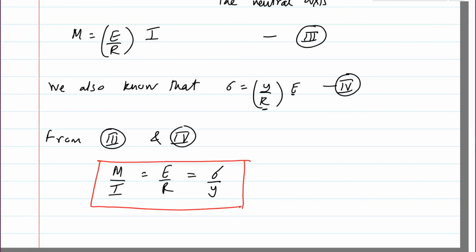You know the y. y is the distance from the neutral axis. So for a given distance, if you want to find the stress on the surface, then you'll put y equals breadth divided by 2 or height divided by 2. And then E is a constant and R is typically unknown, which you can also find using this. So you can tell how much this beam has bent due to the moment M.